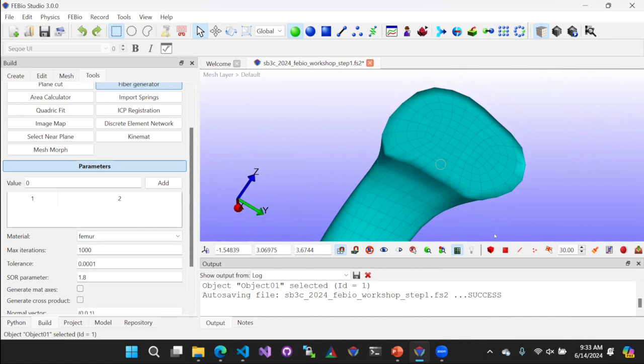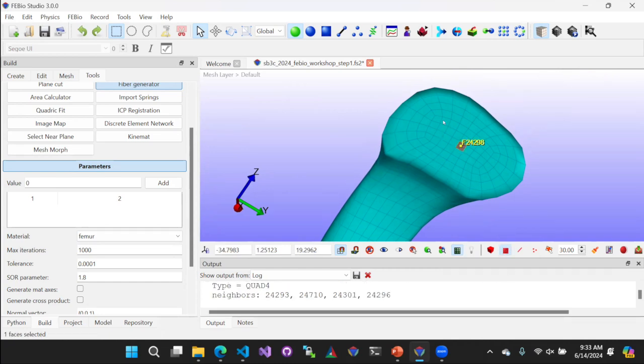So once the green is selected, select on the red face, and now we can select facets on our surface. Okay, so there's the first way of selecting facets. You click on a facet. If you want to add to that selection, you can shift click, but you can see that that's probably going to take us a while to get through this entire surface here. We're trying to select this top surface here.